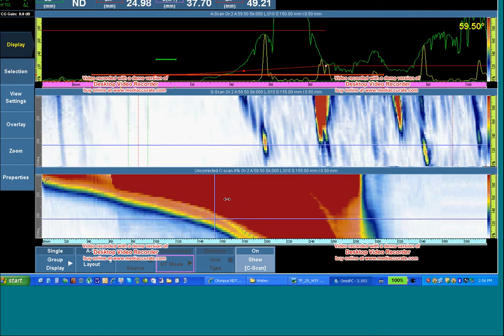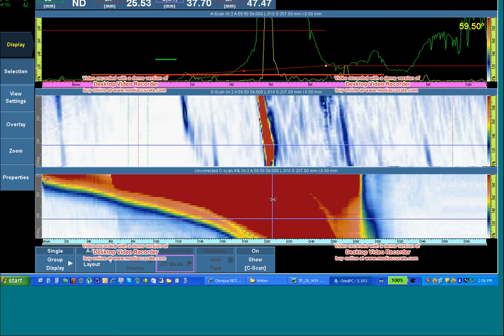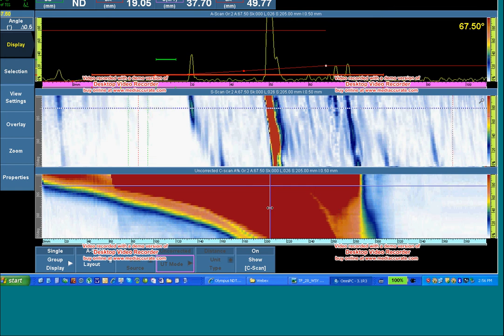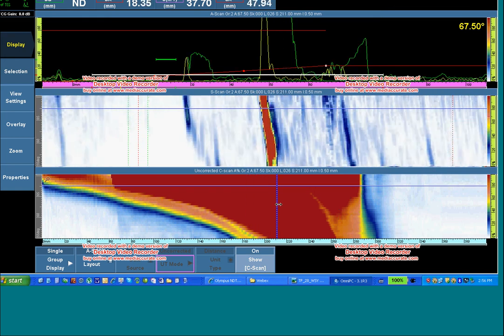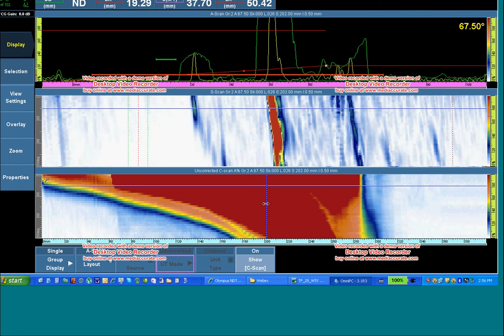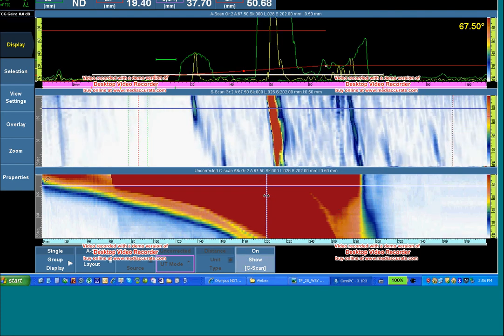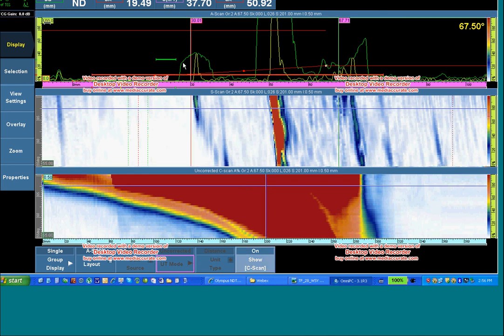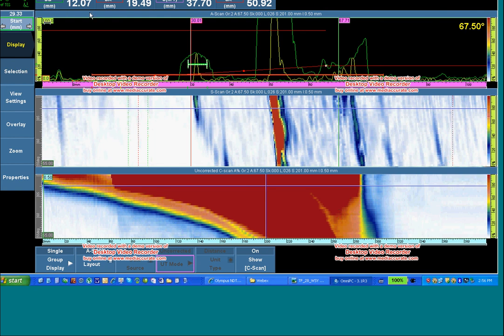So if we take a look at our deepest tip, like we see right here, and peak it up, we'll change the angle to the tip, and I'll move the data cursor back and forth representing the probe. The envelope feature on this A scan helps me identify the very peak. And if I move my green gate directly over that, we'll have a depth of 12.07.